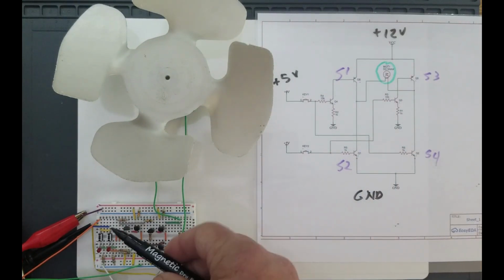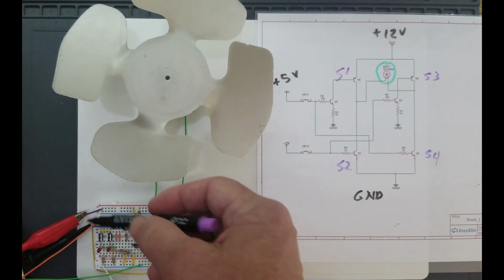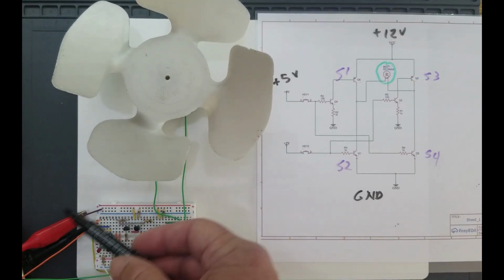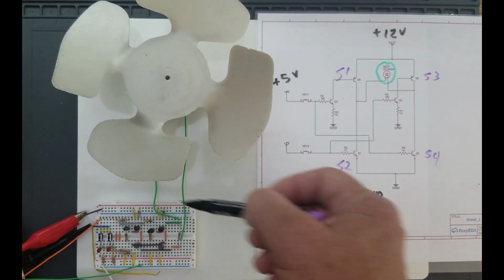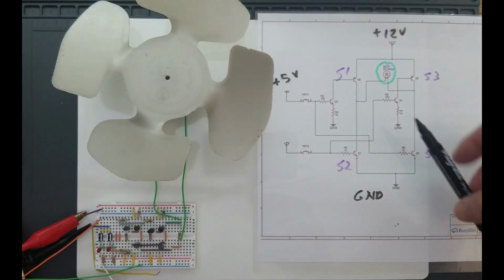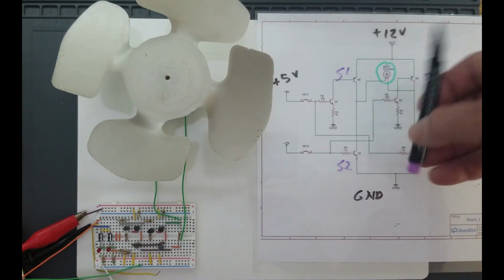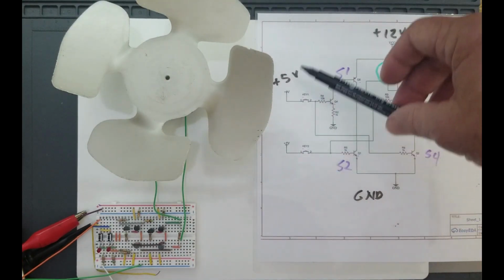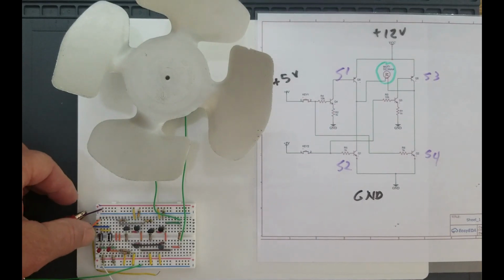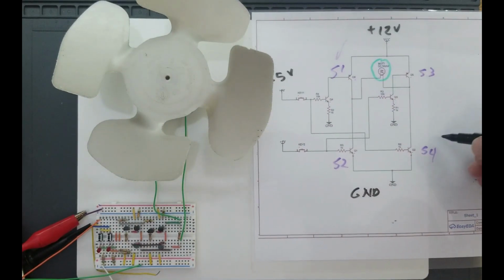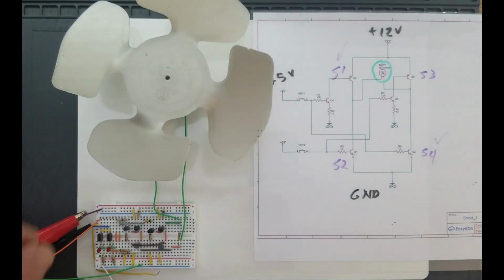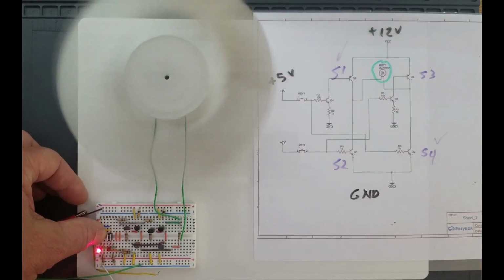Over here, we have a 5-volt source that represents the microcontroller input, and of course we have our 12-volt source to supply voltage to the motor. So in effect, controlling the motor direction can be done with simply 2 control lines from the microcontroller. By pressing this button here, this effectively closes switches S1 and S4 and causes the motor to turn counterclockwise.